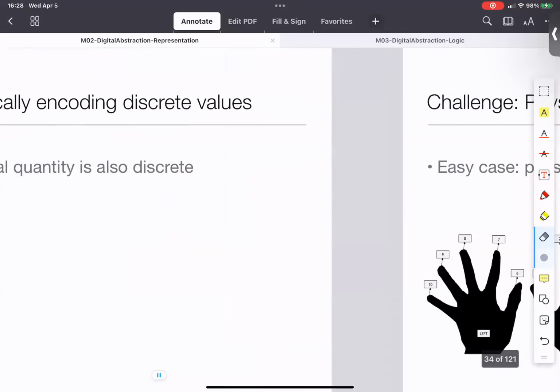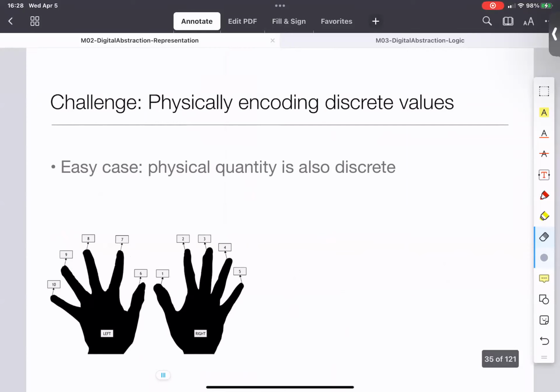So again, our journey is we start with generally analog signals, we sample them, we discretize them, then at any given time instant I get a value which belongs to a discrete set. We somehow map that member of the discrete set into some bit pattern, and we talked about how you need at least log 2 n bits in that pattern. And now we have to take these bits and go back to a physical thing.